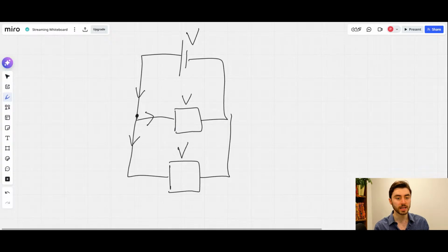Because the electrons here, and here's another top tip: if there is no resistance between a point on the circuit and another point on the circuit, then those two points have the same potential. So here, you have all of the V potential left, which means at this point you haven't lost anything, so you must have all of your potential V. And you can think about the same thing on the other side.